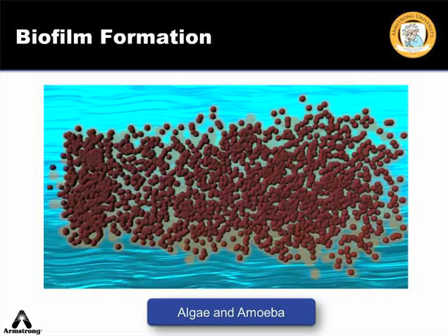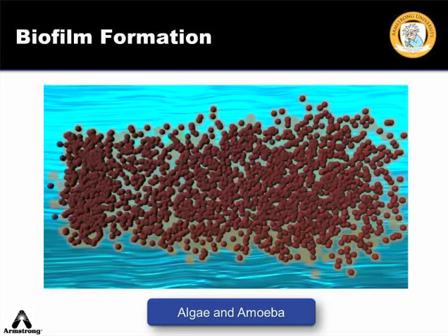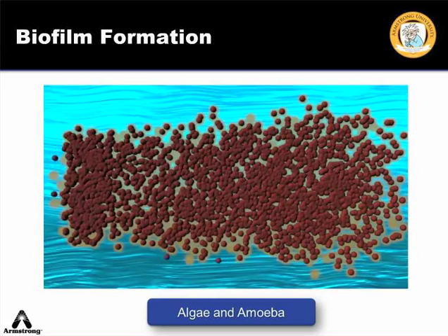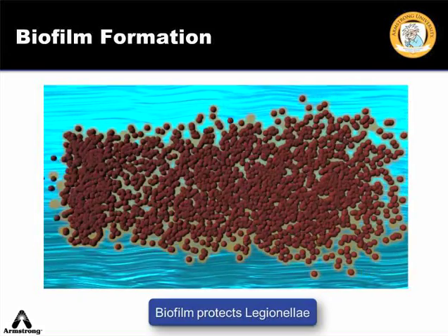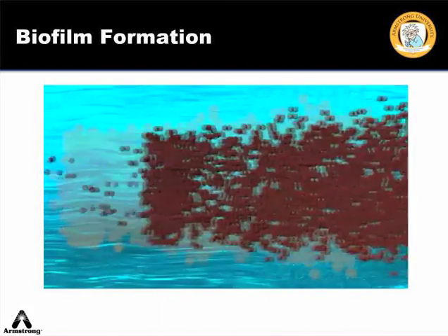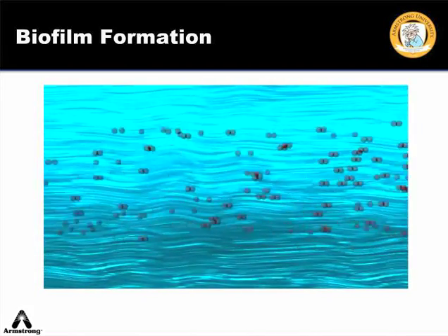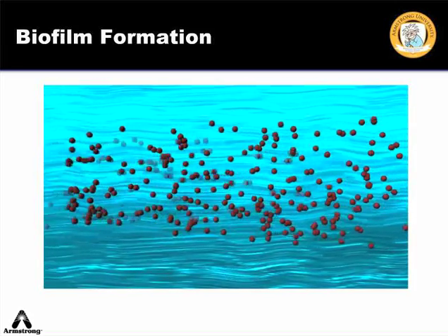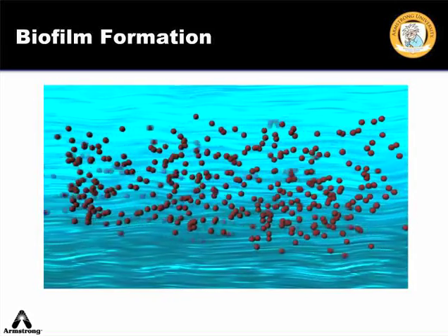A buildup of Legionella bacteria can exist inside the biofilm of a water heater storage device where it typically colonizes. The biofilm essentially protects the Legionella. If the hot water system experiences water hammer due to hydraulic shock, dangerous levels of Legionella bacteria could potentially be released from the biofilm.